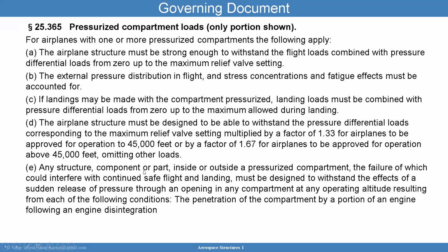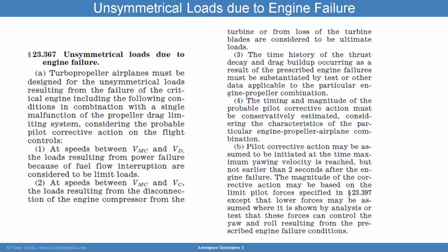Any structure, component, or part inside or outside of a pressurized compartment, the failure of which could interfere with continuous safe flight and landing, must be designed to withstand the effects of sudden release of pressure through an opening in any compartment, that's the fuselage, at any operating altitude resulting from each of the following conditions. Penetration of the compartment by a portion of an engine, so you have a blade cracking and then it hits and punches the fuselage. You need to survive that. You don't want an explosion that causes the whole airplane to come down.